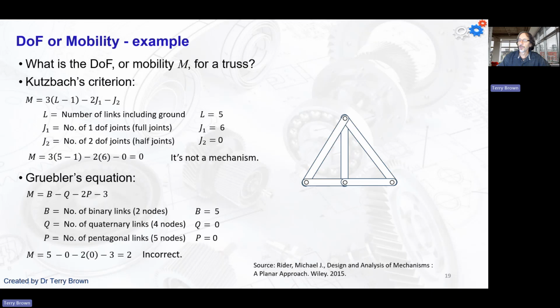If you think about it, you could treat either one or the other of these 2 triangles as just a single binary link. So it doesn't matter if we make our triangle with three pieces like this, or our triangle is made like this. If you look in the picture, the video of me on the side there, I've got a triangle. You could have it like that, then this point here is just part of the rigid link.